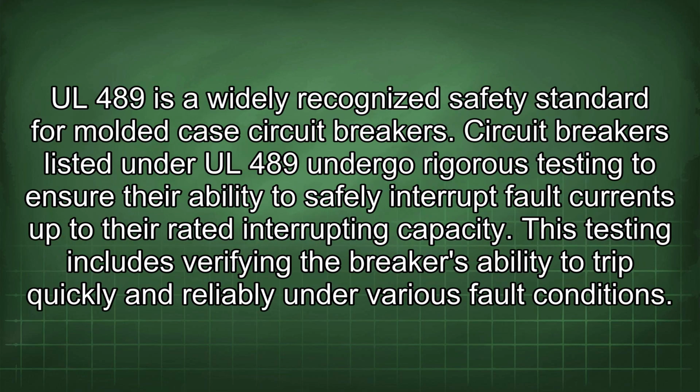UL 489 is a widely recognized safety standard for molded case circuit breakers. Circuit breakers listed under UL 489 undergo rigorous testing to ensure their ability to safely interrupt fault currents up to their rated interrupting capacity. This testing includes verifying the breaker's ability to trip quickly and reliably under various fault conditions.